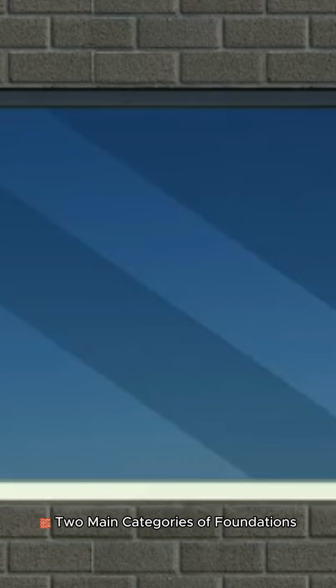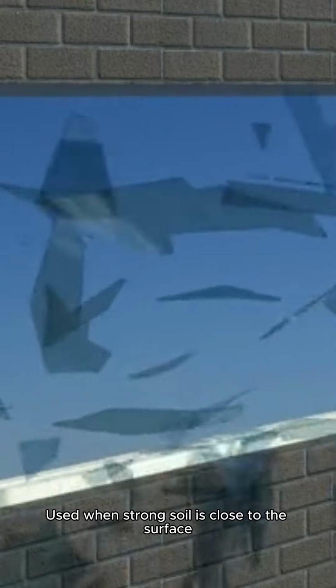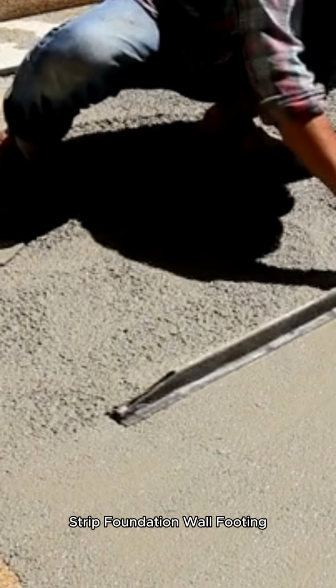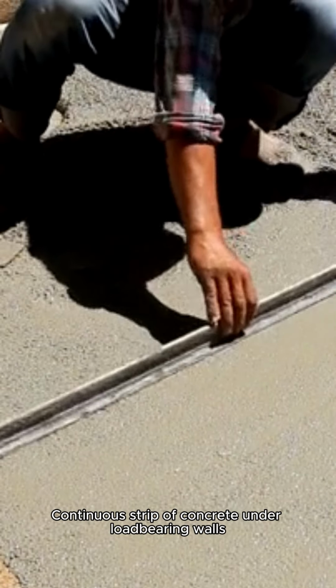Two main categories of foundations. 1. Shallow foundations, also called spread foundations, used when strong soil is close to the surface. Types of shallow foundations. Strip foundation, or wall footing: a continuous strip of concrete under load-bearing walls.